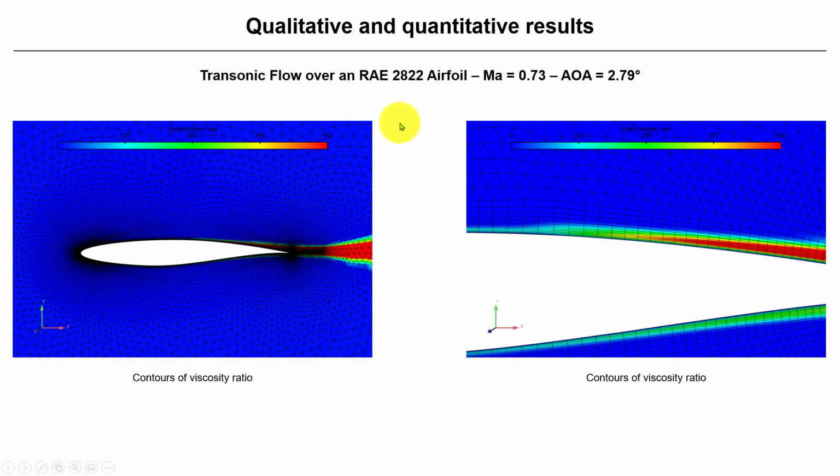Contrary to what we did previously, where there was transition modeling and we had verified, very good meshes, look here in the rear part of the airfoil: we're getting that transition from the prismatic or rectangular cells to the triangular cells quite fast. When I talk about adding numerical diffusion due to that transition, probably here you see it. So this is very important to control.